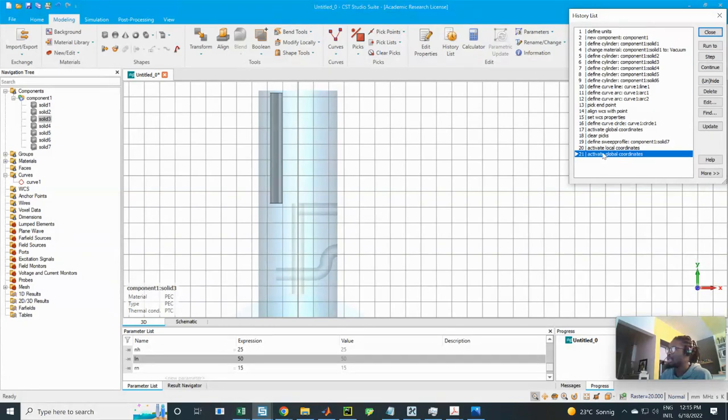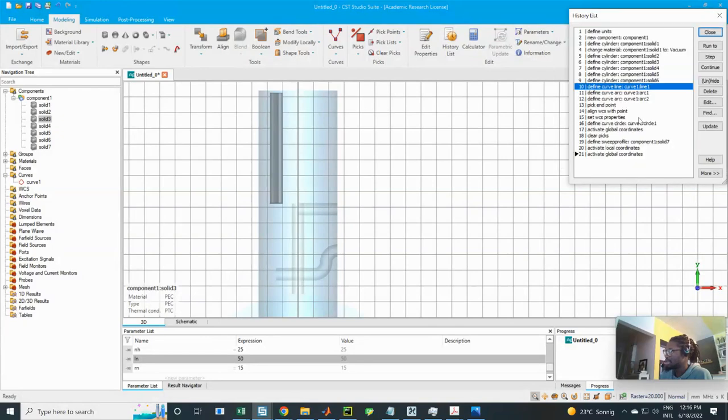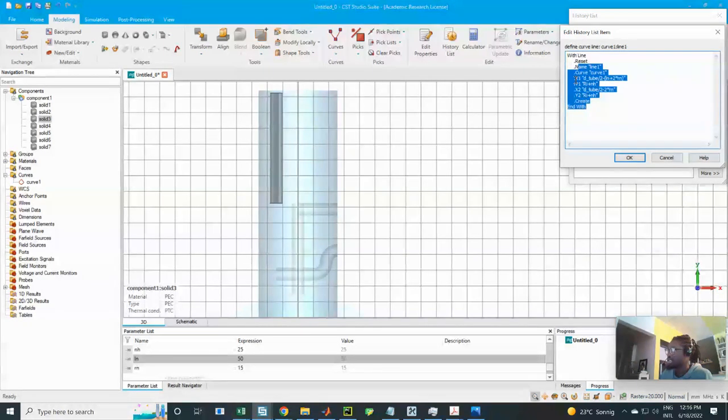But when you make your changes in the curve and your local coordinates, it doesn't automatically get updated in the past. If you want to make a change, you would have to come to the history block and edit it from there. That's why, for now, just consume the sketch. Forget what I said initially, just consume the sketch. Because if you still have the sketch here, you'd be tempted to work on it instead of going back in time to change the dimensions that you need.